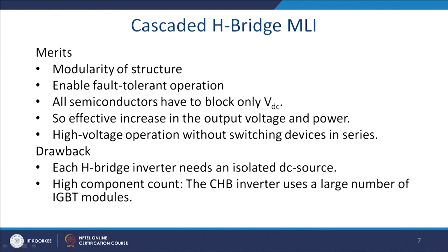You just increase the number of levels, and when the voltage level changes, you can have the same inverter configured and put into applications. It is effective to increase the output voltage level and the power, with high voltage operation without switching devices in series. These are a few advantages of this cascade multi-level inverter.